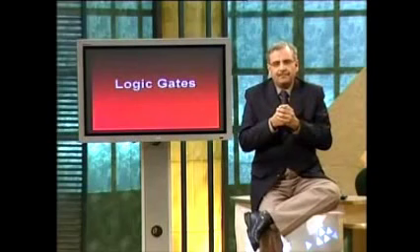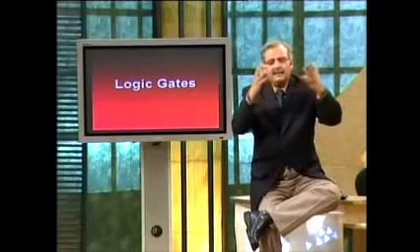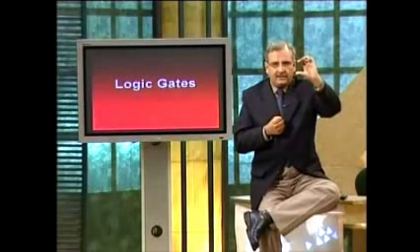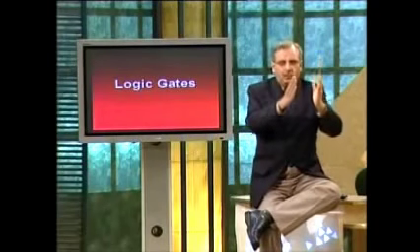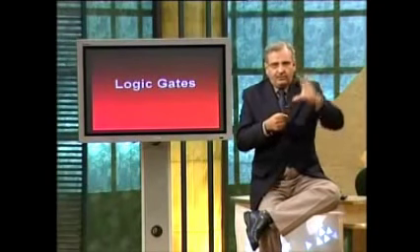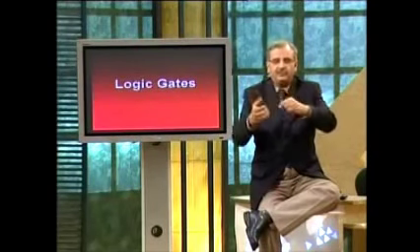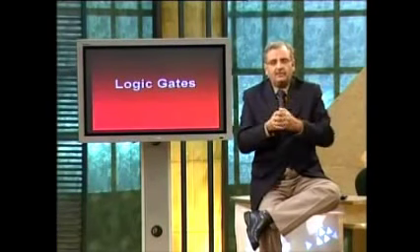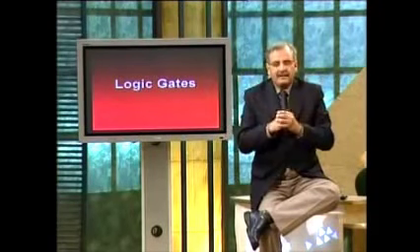So how would you convey that information, that how a gate works during that 10-second interval? Through a timing diagram. When we describe an AND gate or any other gate, we would be identifying the gate through its symbol. We would be describing its function through a truth table or a function table. We can also write an expression which represents the operation or the function of the gate, and we would also be describing or writing out its timing diagram.